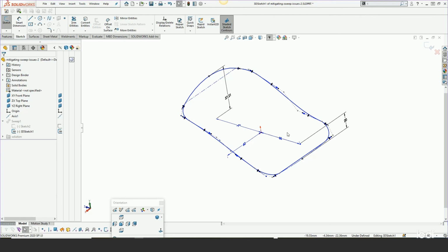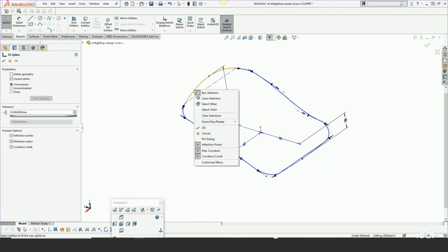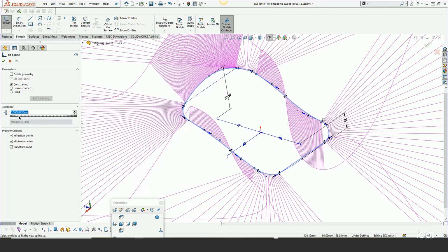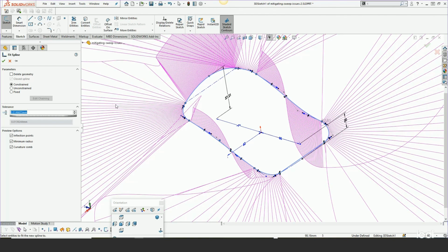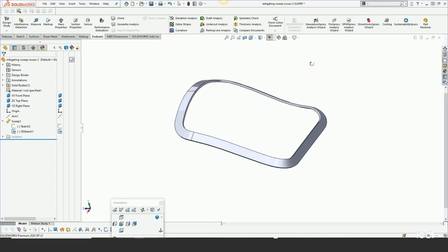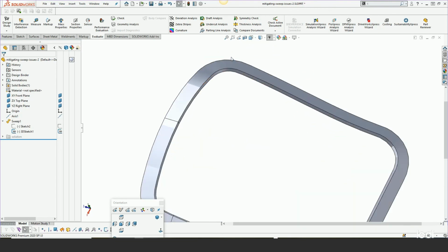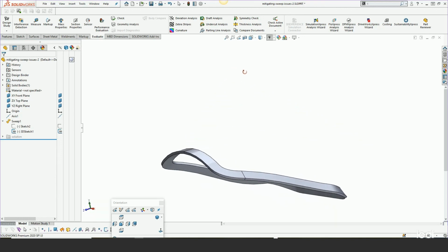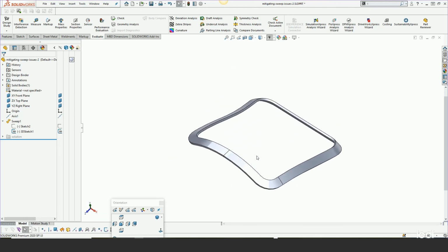And you can do that with the fit spline feature. So I have it on my shortcut key because I use it a lot. So I'm just going to pick this chain and fit a spline over it. And bring the accuracy up a bit. And now that we fit a spline over that, voila, we have problem solved. And namely, it is just sweeping along that single spline, and it can understand much better how to migrate that profile along the path.